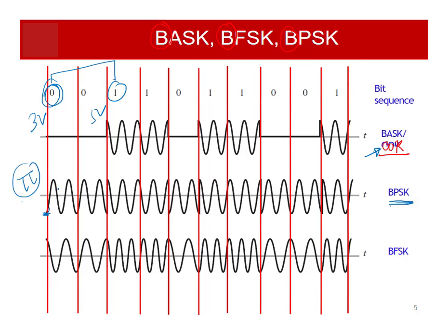So it goes high, then again negative, positive, negative, and from here it is another bit starting, and it is again starting from -1 because it is 0. So it starts from -1 and goes on and on. Here is the transition. You can see now the bit is 1. So for 1, it will start from +1. You can see there is a clear transition between this 0 and 1, and now we have the same signal but with a different phase. Previously for 0, it started from -1, but for 1, it is starting from 1.